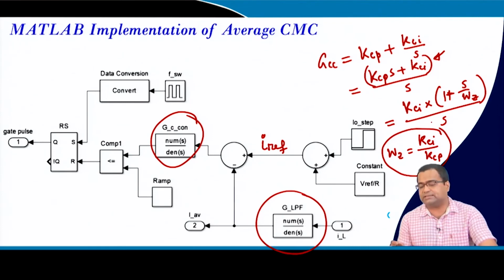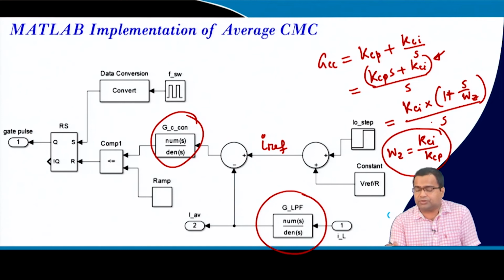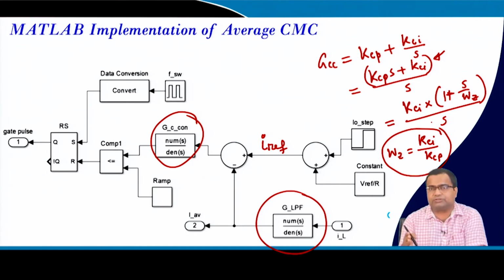I want to place this zero because this will ultimately go into the closed loop control. So I want to take it close to the imaginary axis, so I want to reduce the integral gain, because earlier I made a change, I have decreased this.